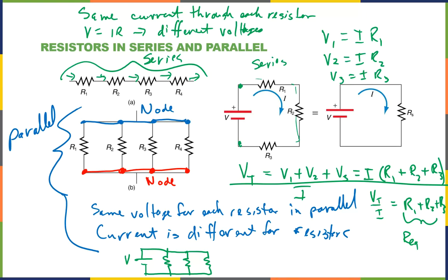what's the same for all of the resistors when they're in parallel? The current. No. That was for series. They all have the tops connected together. They all have the bottoms connected together, so they have the same energy per charge. What do we call that? Voltage. They all have the same voltage.